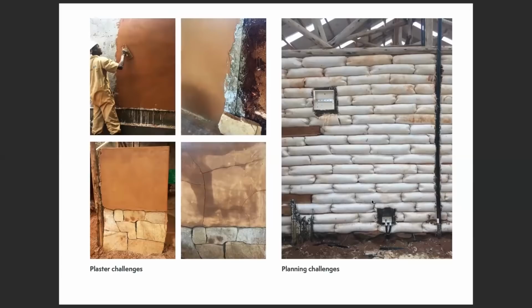Another lesson learned applies really to any building, not only to this particular one, and that is plan well, think about your services very well, and provide a lot of information prior to going on site. But the real interesting part of the picture on the right that explains how the services are installed is that there's a bit of a difference between earthbag and, let's say, a concrete blockwork wall, and that is that things are not that easily fixed to it, and therefore they need to be prepared.